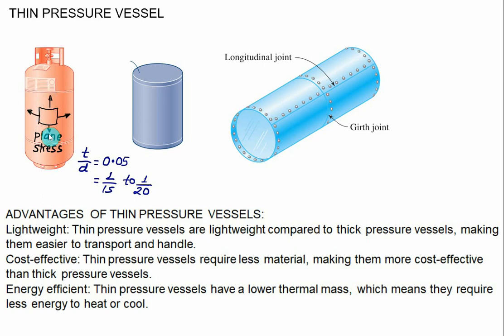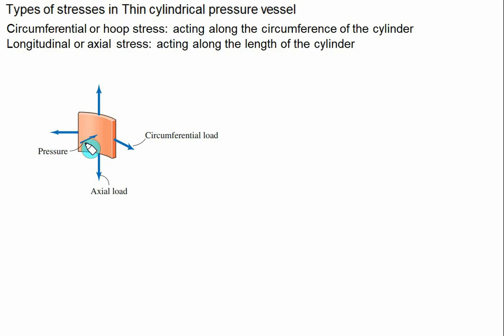that is along the axis of the cylinder. Longitudinal axis, we will develop here the longitudinal stress equal to sigma L, and along the circumference will develop here the hoop stress. So as shown in this figure, we have diameter is very large and thickness is very small. So in this case d by t ratio, that is the diameter to thickness ratio, is very much greater than 1. This one is representing the axis and this one is representing the circumference.